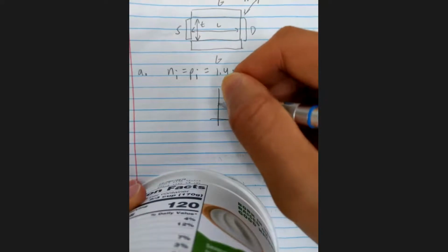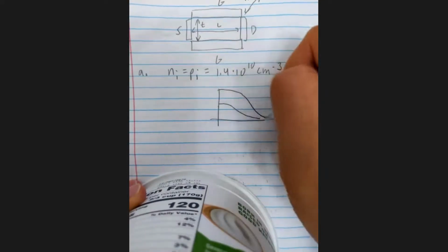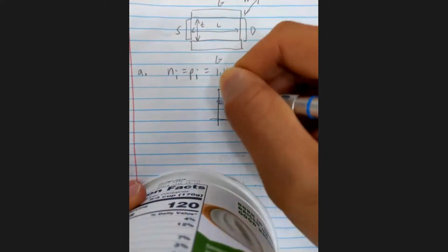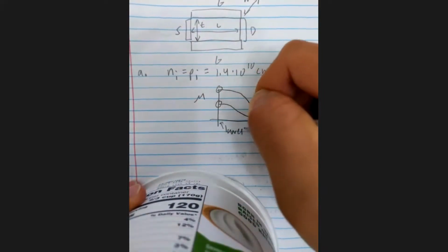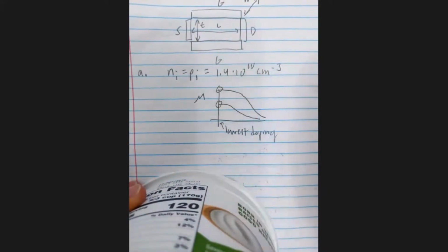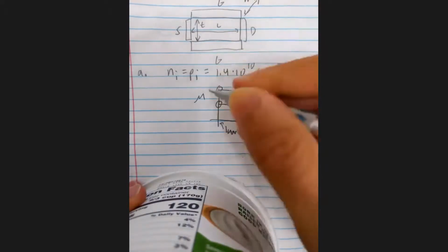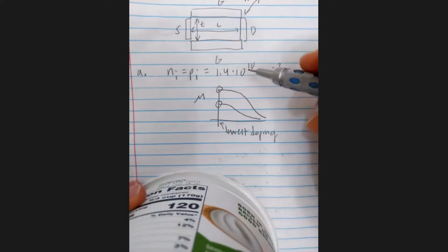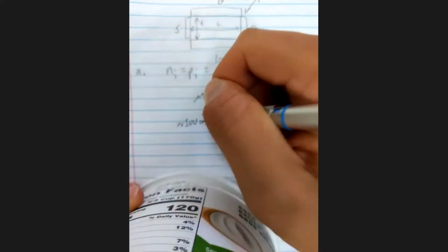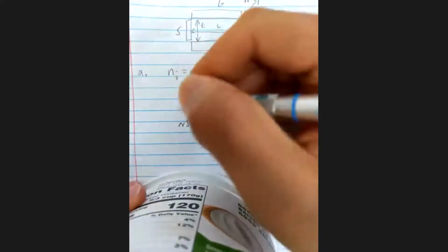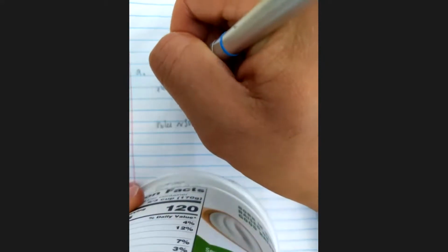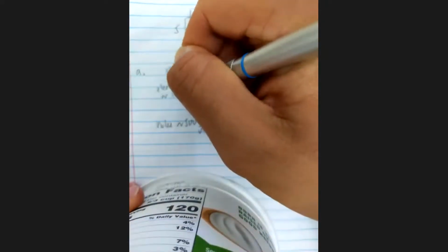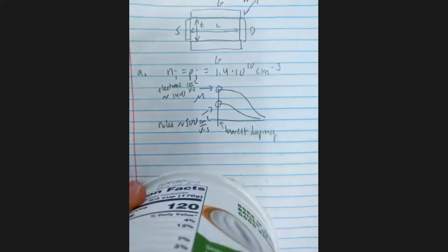For silicon, they're going to look kind of like this, and this is given in the front matter. But we're just going to take the values of the mobility at these two points, which are the lowest doping, to be the values of the mobility that we're going to see with intrinsic silicon. These values are around 500 centimeters squared per volt second for holes, and for electrons, about 1400 centimeters squared per volt second.